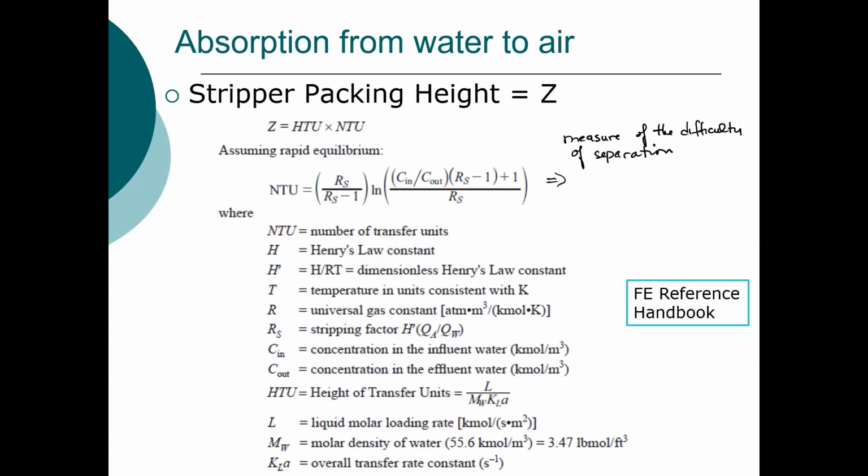And as was the case when we talked about adsorption processes, if we have one NTU, this is going to result in a change in composition equal to the driving force providing that change.